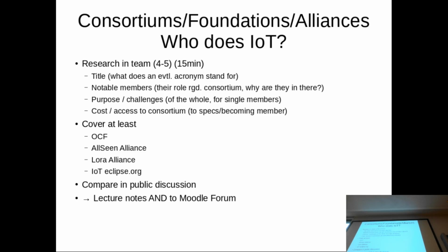So you guys haven't found much about LoRa, yeah? So we will have that later in class. So LoRa is a cool kind of open technology to use a low frequency band to send messages over an incredible distance. So you can actually get your own LoRa equipment for less than $50, and then send things over 12 kilometers if you have line of sight, with a very low baud rate.